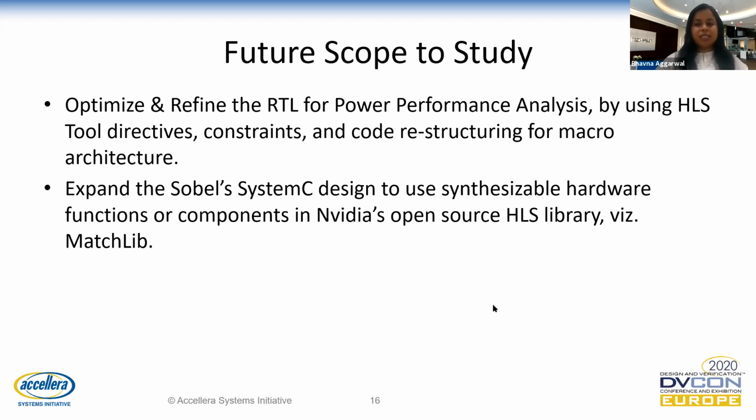To maximize the HLS capabilities, both software and RTL design engineers can collaborate to develop the ASIC or FPGA solution at the earliest. Also, software test engineers and RTL verification engineers can collaborate to validate and verify the solution in parallel, thus minimizing time to market by apportioning both design and verification responsibilities.